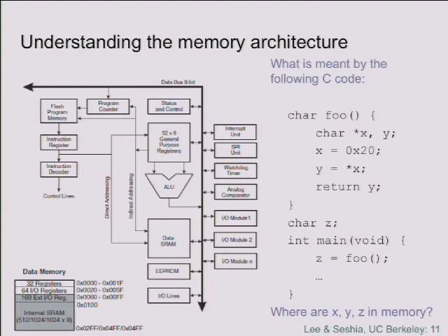This is, by the way, a nice abstraction mechanism. I would like to know what my accelerometer is telling me. I could write a procedure that says accelerometer data, okay? And then I just call that, and I don't have to remember what memory register it's at and so on, okay? So this is going to return whatever is in that I/O register.